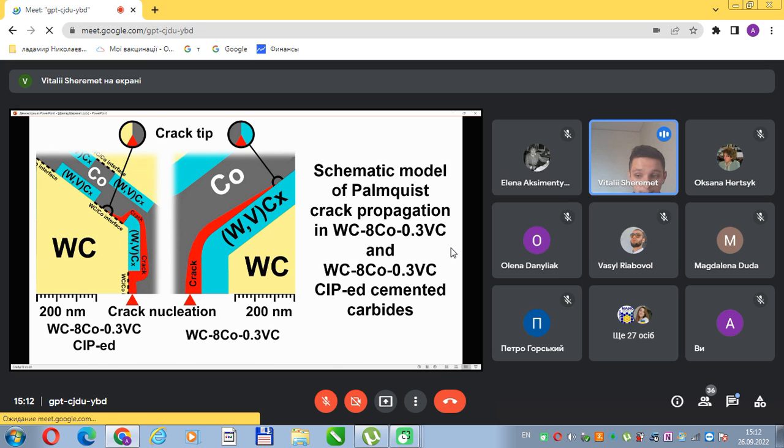From the results, it can be seen that such change of the morphology of tungsten carbide grains can change the proportion of the crack along the interface and affect the fraction of the tungsten carbide cobalt interface coherency. The results confirm that cold isostatic pressing dramatically increased the fracture toughness of the cemented carbide.